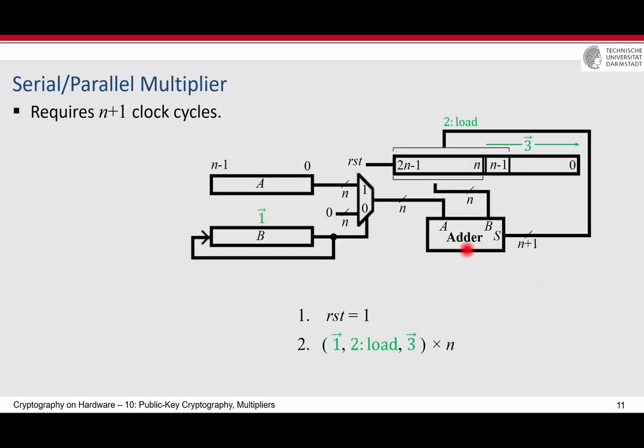It means that in one clock cycle, you do reset. In the next clock cycle, of course, everything, as I said, is available here, combinational. But then B is rotated 1 bit, and this part loads n plus 1 bits here, but at the same time, you need to shift the rest of the values which are in the register, from this bit. It means that we should not ignore the n minus 1 bit. Then this is shifted here, and this should be repeated n clock cycles, and then in n plus 1 clock cycles, you have the output of the multiplier.